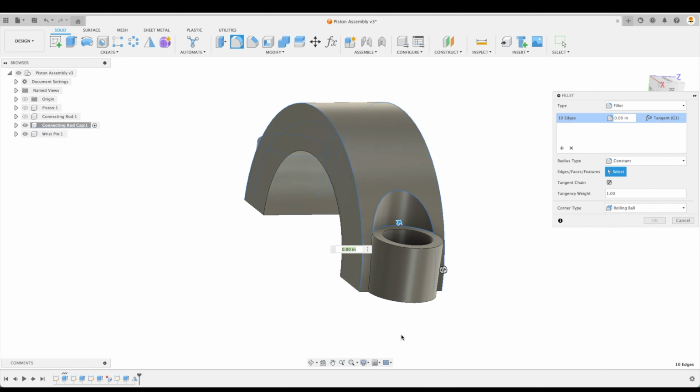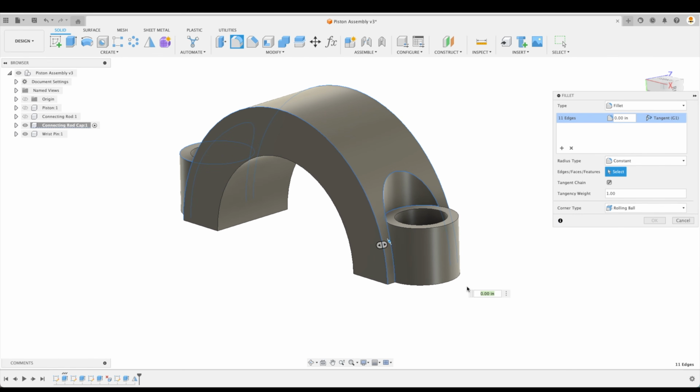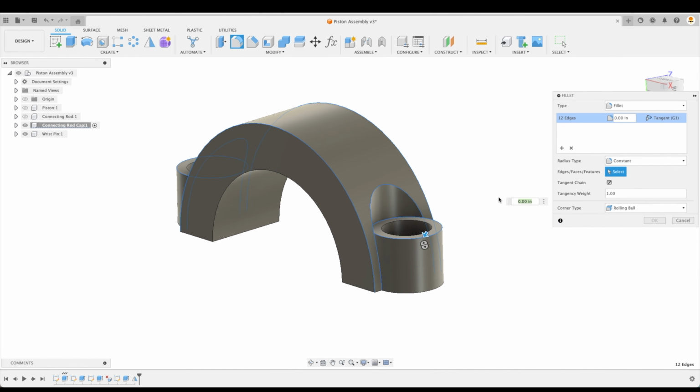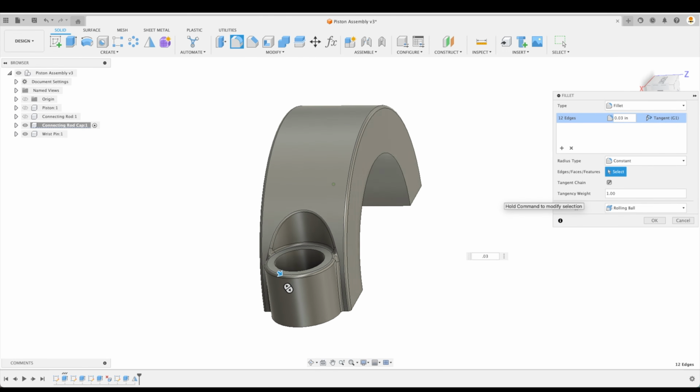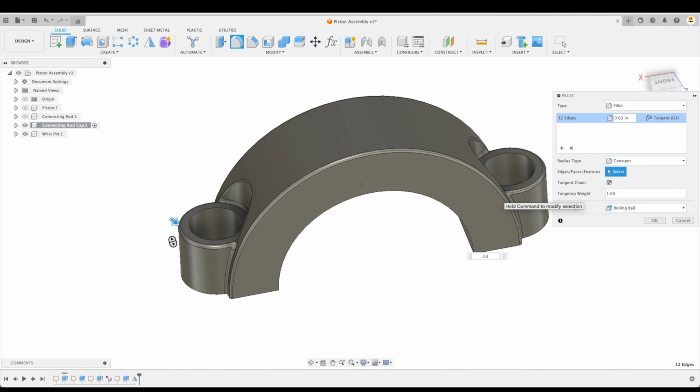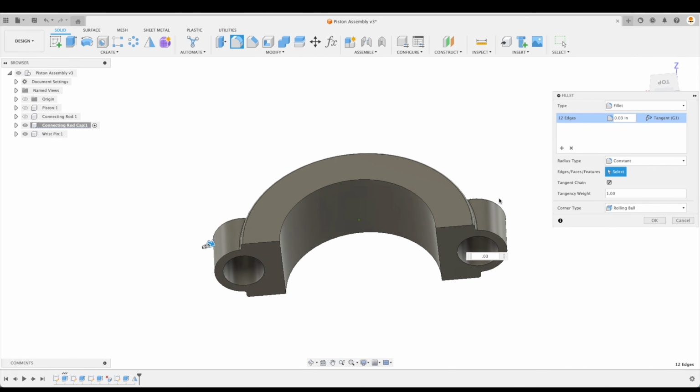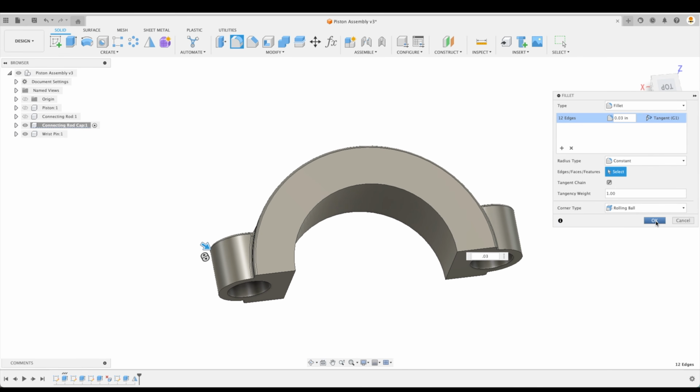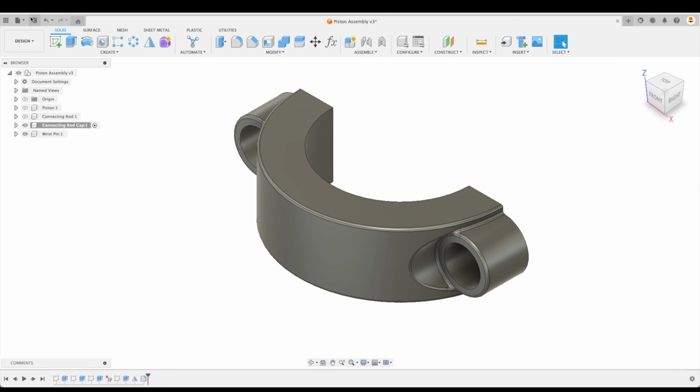And if you ever see that on a drawing, that edges remain sharp, we just don't add a fillet to it. So here we break the edges, and is there a specification on our drawing? Yes, it's 30 thou. And if we go 30 thou, well, everything gets filleted at 30 thou. Great. Okay, done. Let's save that.